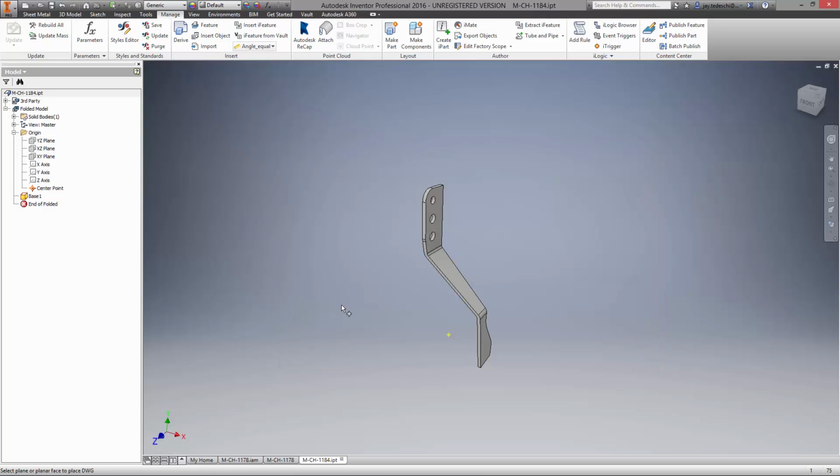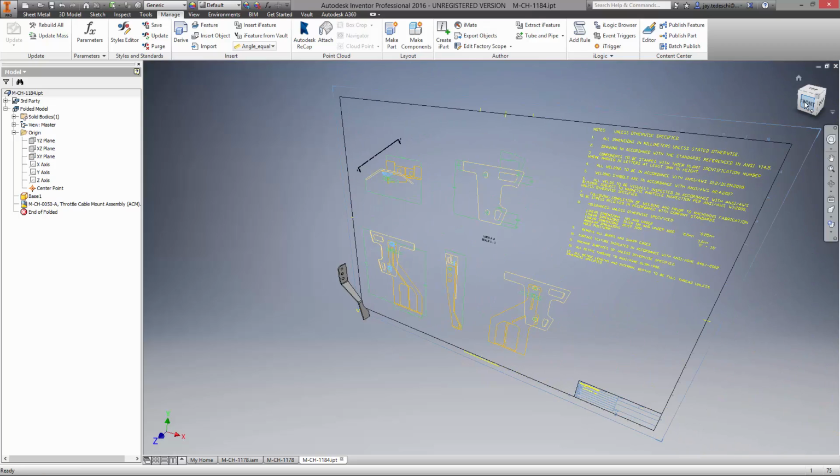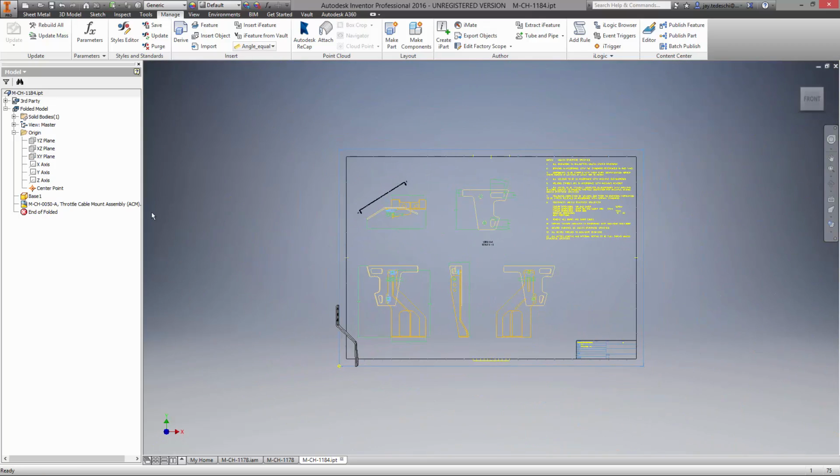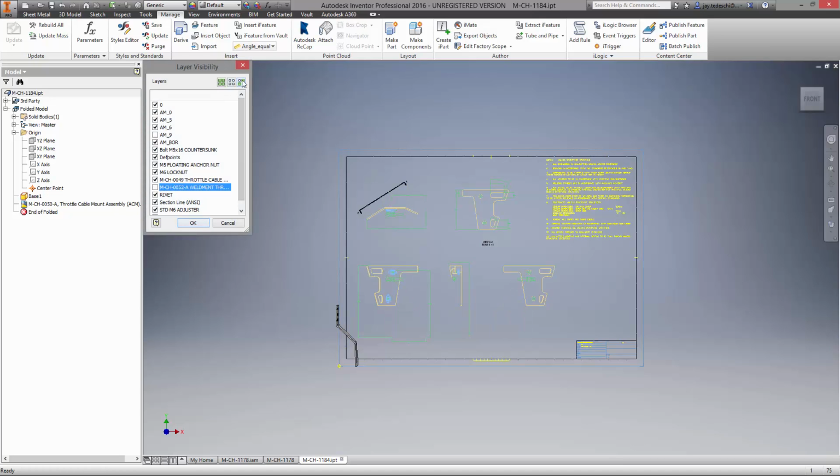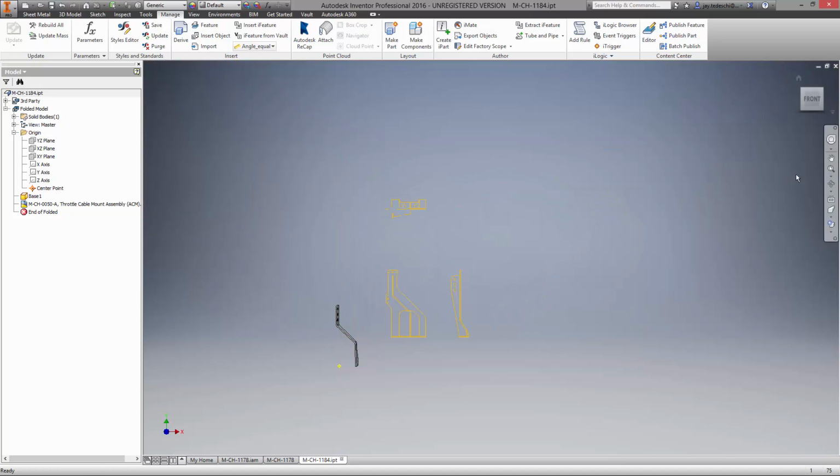Here we'll take advantage of a detailed drawing for the other sheet metal body using DWG underlays, new in Inventor 2016. Layer capabilities are available to turn them on or off for optimal clarity. Everything in the drawing is associative back to the AutoCAD file. If any changes are made, it is reflected back here in Inventor. Before using the entities to make the model, we'll position the view next to the other sheet metal body.